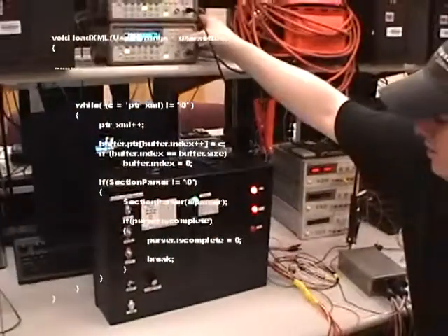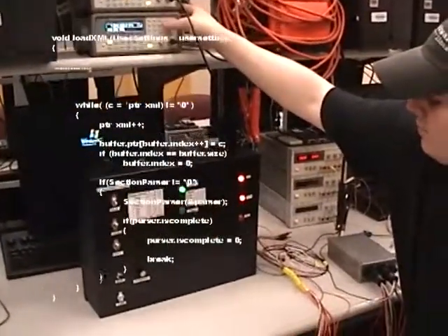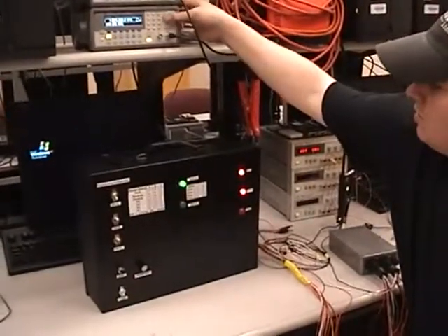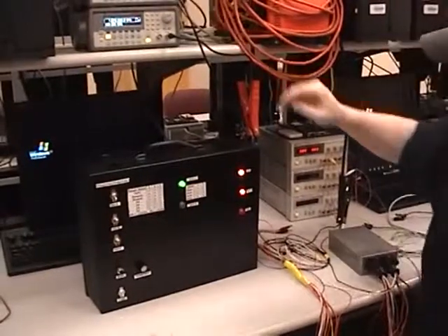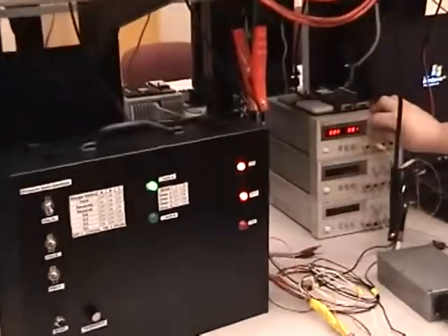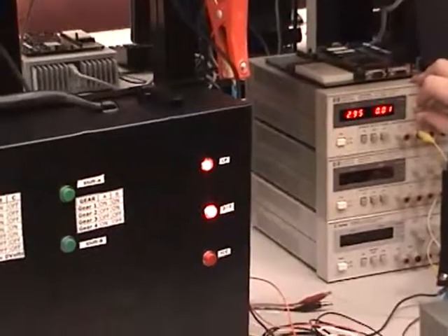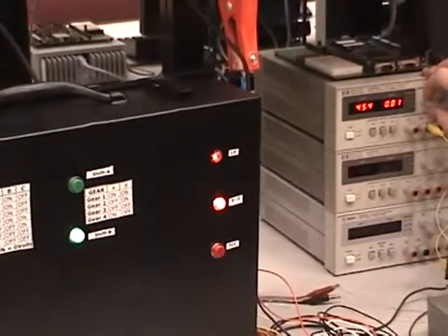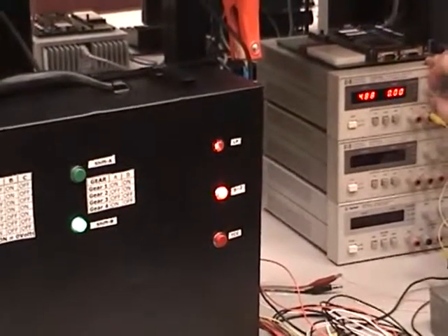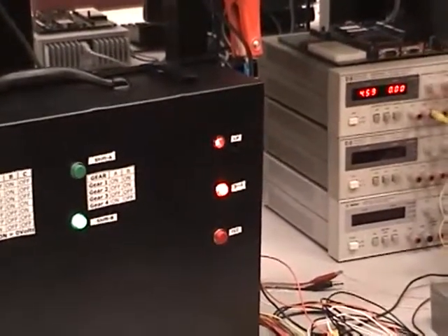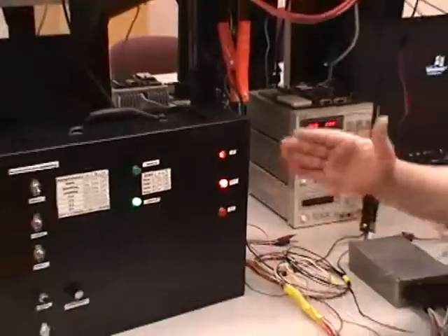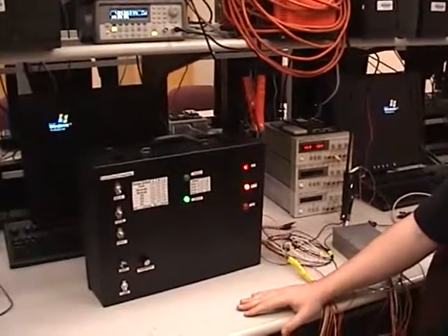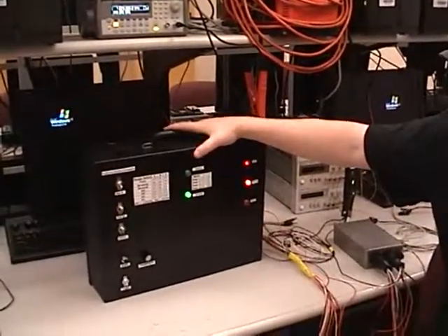So now we'll see where fourth gear currently goes off, and it's around 1.2. And then we'll try it now and turn the throttle all the way up. That's third gear. And then you see it shift all the way from fourth gear to second gear with our new configuration file. So this is more for you performance users that really want your car to just drop to a low gear, have a fast hard takeoff. That is your particular configuration.